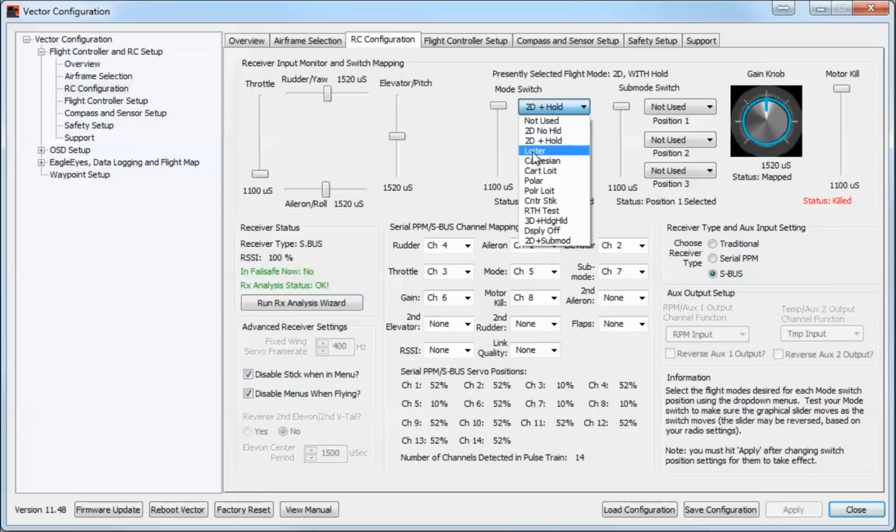It's the equivalent really, if you're used to DJI, of the GPS mode. So it will actually stay in a fixed position in space, it will stay at a certain altitude, and it will hover there. If wind strikes it or if it finds ground effect, it's going to fight against that because it knows that it's supposed to be staying in that one GPS mode. It's not a case of when you flick it into loiter mode that you have no control over it. It's not designed to just fix in one position.